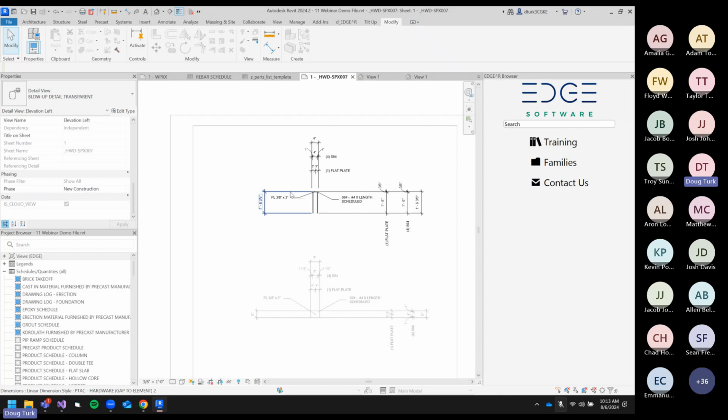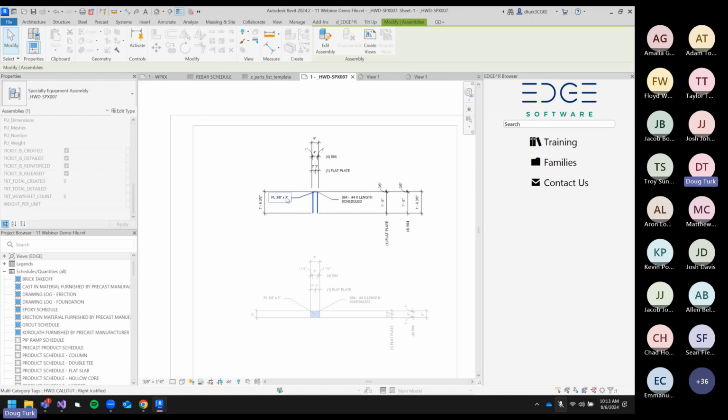So if you have an empty family with several things with geometry nested into it, the empty family will receive a 0 with the children receiving values. If, however, that top level has geometry, it will receive a value. So you're only receiving weights for the solids that are in that family level. Which is why the top level is not getting one here, because it doesn't have geometry.